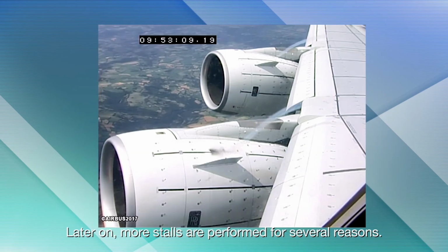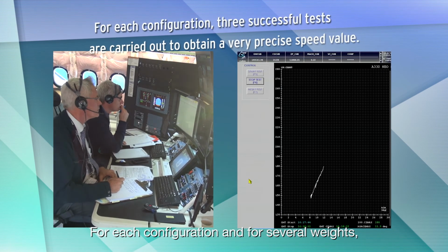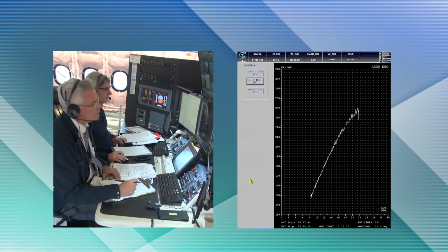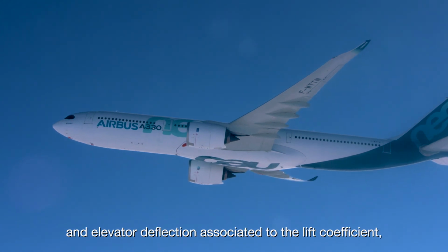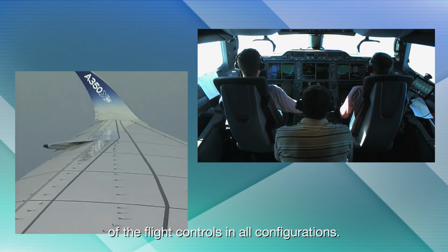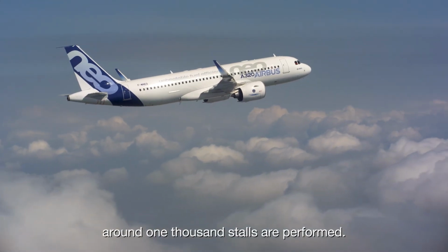Later on, more stalls are performed for several reasons. First, the stall speeds are used to compute the aircraft performances. For each configuration and for several weights, 3 successful tests are carried out to obtain a very precise speed value. In addition, the stall characteristics and also the angle of attack and elevator deflection associated to the lift coefficient need to be identified for the fine-tuning of the stall protection of the flight controls in all configurations. During the flight test campaign of a new airplane model, around 1,000 stalls are performed.